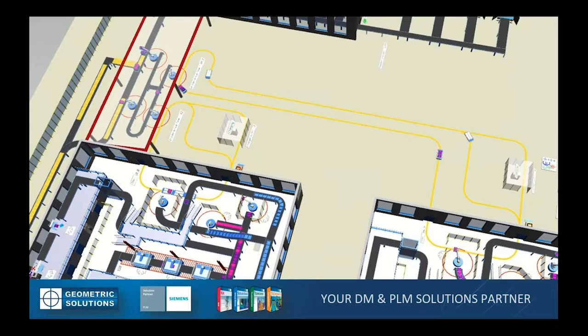There's usually a master controller. We can test all that logic and the switching up front and actually tie in the PLCs, whether it's hardware or, I'm going to call it, software in a loop, where we simulate the PLCs to this tool and actually test the coding that goes into that.